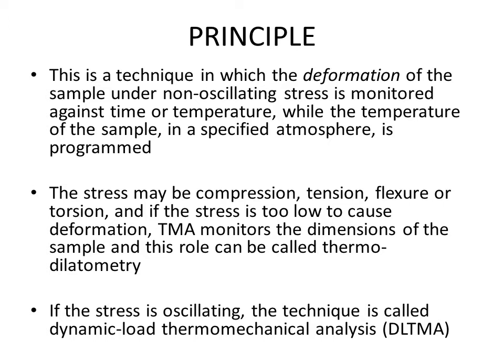And what type of deformation is going to happen in the sample is monitored against time or temperature, while the temperature of the sample in a specified atmosphere is programmed. So the temperature is properly programmed and the atmosphere is specified, means what type of atmosphere you have given to your sample. So we study the deformation of the sample under this non-oscillating stress.